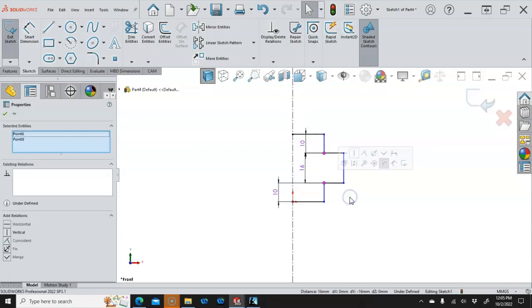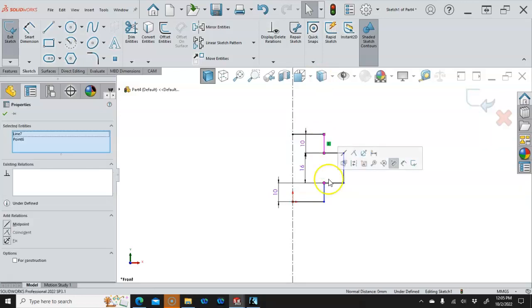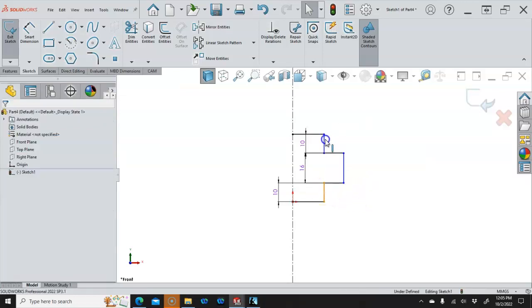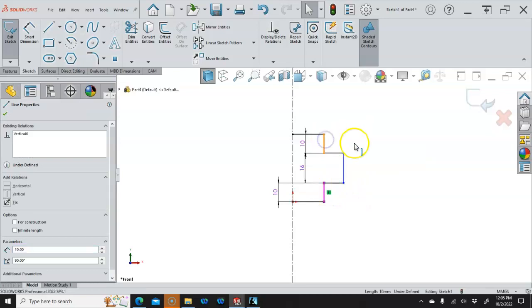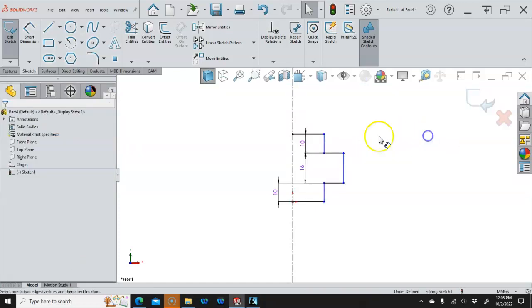If I go to the points, those are going to be vertical. If I go to a line and the point, so like the line and the midpoint, those would be coincident. Midpoint wouldn't be a good choice there. But the easiest targets to acquire are the two object lines, making those collinear. All right, and then our diameters are going to be 10 and 14.